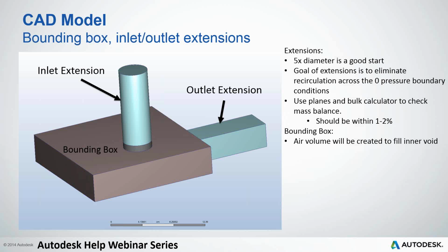Now in this model, as you know from part 1, it's forced convection through an internal fan that we used. So the inlets just have 0 pressures. That inlet has a temperature on it too. We can go into that later, but we basically have free flow at the inlet and outlet and a fan in the middle that is doing the work here.